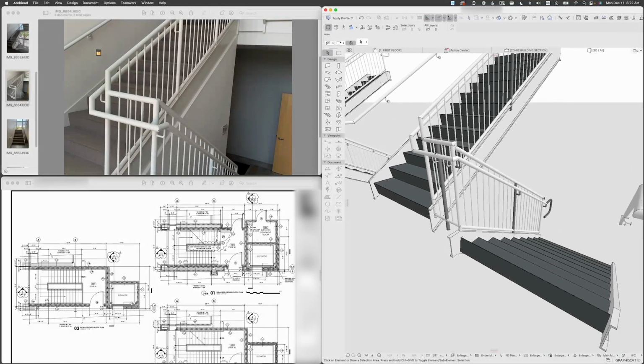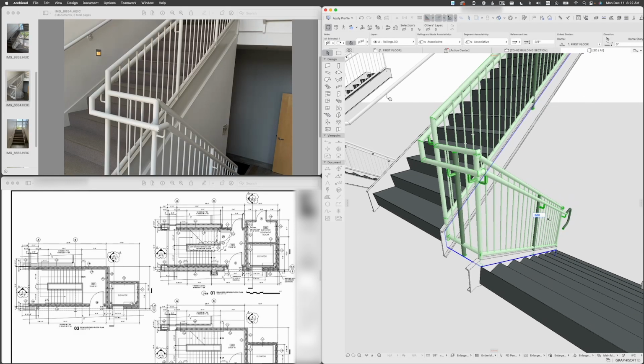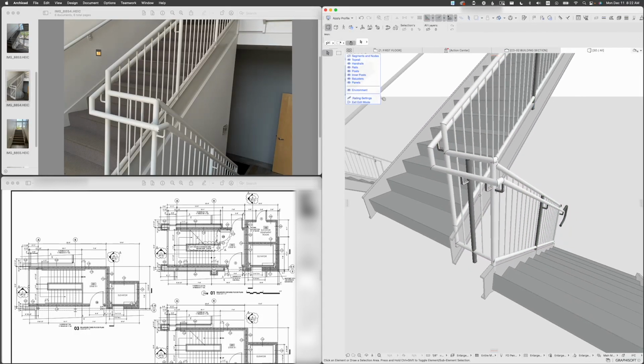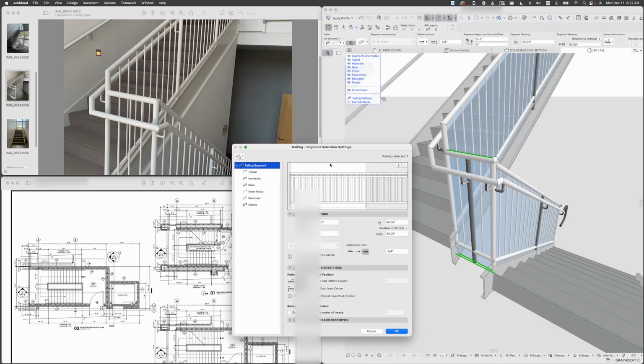Now, a couple of things. We need to check these fixings. So here we see we don't have any fixings on this mid segment. So I would now have to click Edit and adjust individual segments. I will turn on the segments. Now select this segment, go to its settings, and let's see how we can turn on fixings.